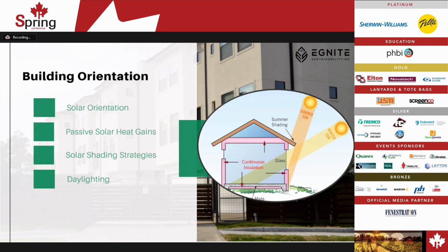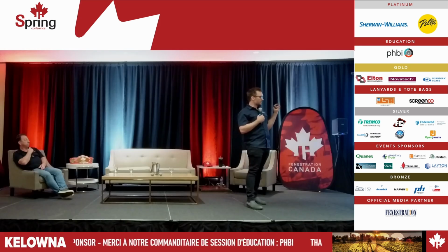But the thing we've got to watch out for is that in the summertime, we get some pretty extreme temperature fluctuations and we've got risks of overheating. So we really want to be careful with what solar heat gain we're speccing on certain facades. Even on some high performing Passive House and Step 5 homes, we're working with the energy advisor and the window supplier, looking at solar shading analysis and which windows we can spec with a higher solar heat gain, and which ones we have to spec with lower solar heat gain.